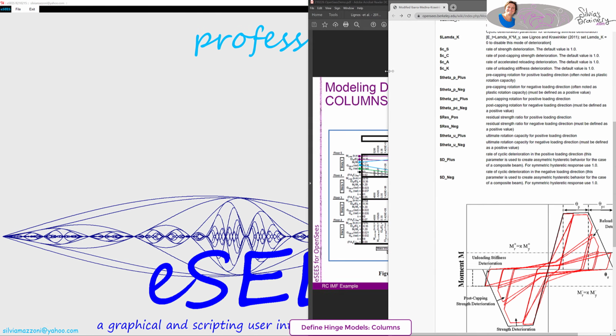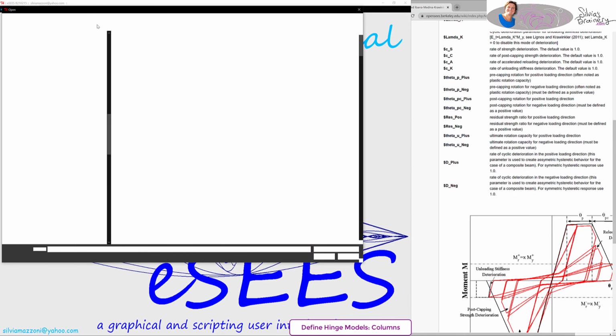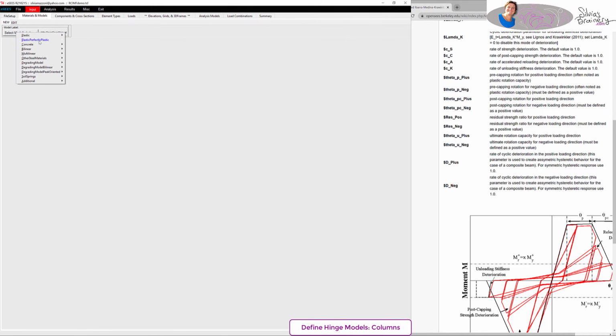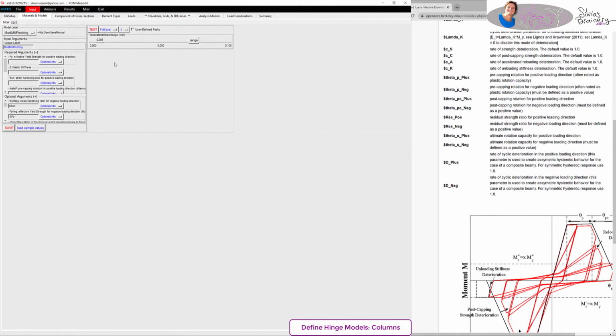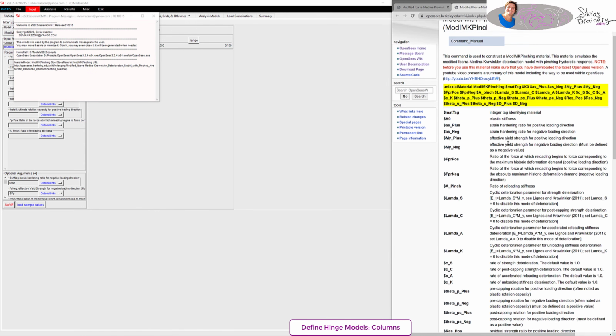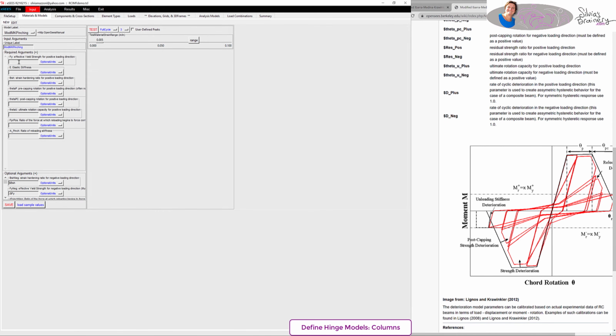The main thing is, how do you deal with that initial stiffness? Because sometimes they only deal with plastic rotations. And then what models are they using for the intermediate? If they're doing a concentrated plasticity model, what are you using for the elastic component in your beam or column? And so I'm kind of going with the data there.